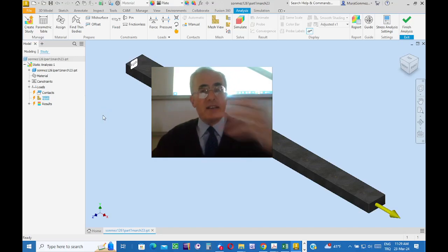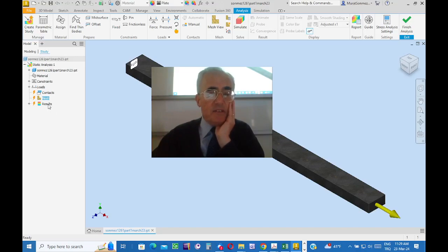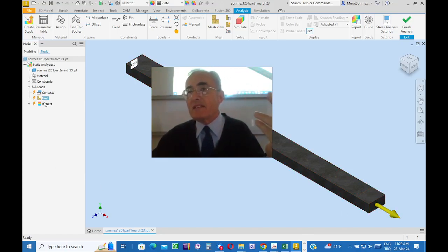I'm going to define the study as a new analysis. But be aware, if you continue in the same analysis, then update the solution and resolve the problem. Of course, although we split the surfaces, if we rerun the software we are going to find the same results, because surface splitting will not affect the calculation.